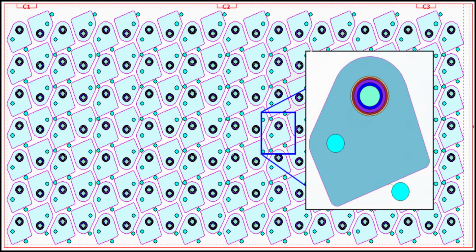Tooling. The tooling software analyzes the rotation of each part and tools each part in the nest. Parts with punch plans like this part are output with 5 individual hits, 1 hit for each tool.